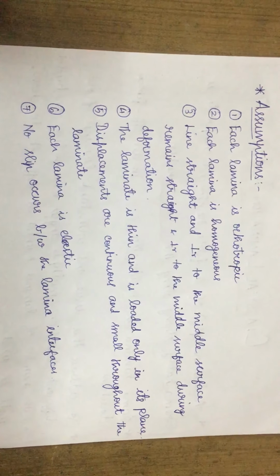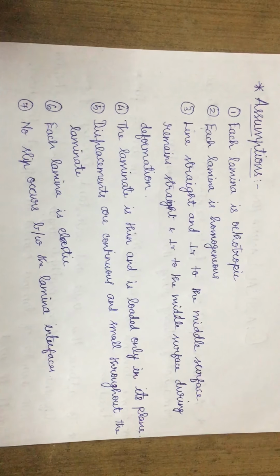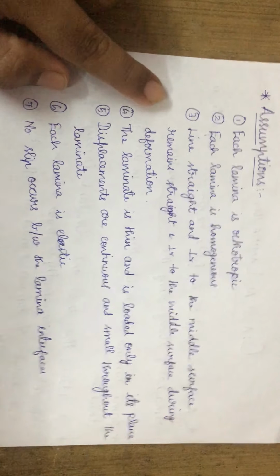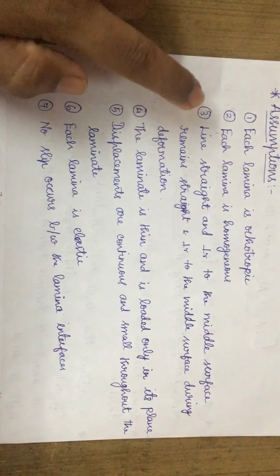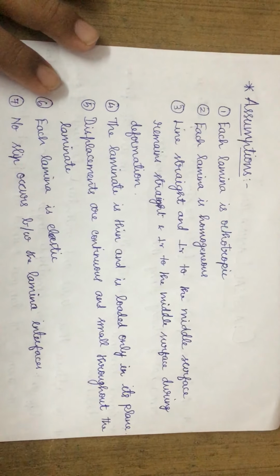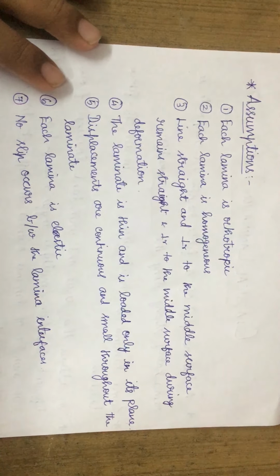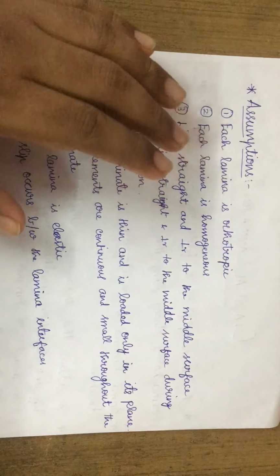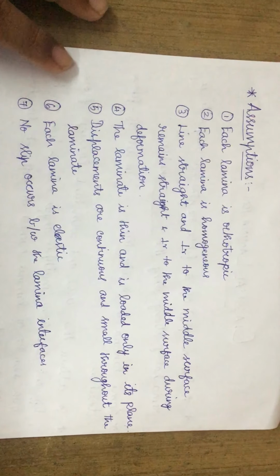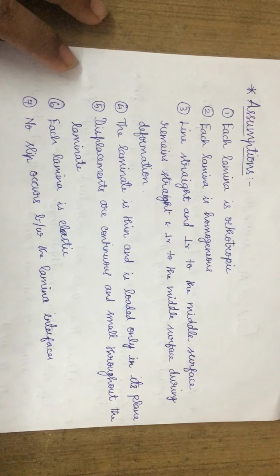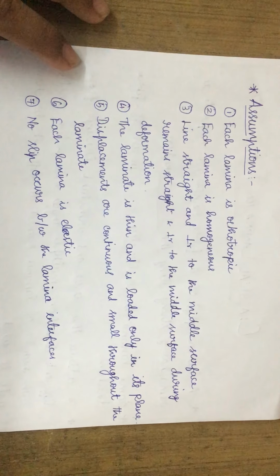The lamina is orthotropic, homogeneous, and elastic. And remember, a line straight and perpendicular to the middle surface remains straight and perpendicular to the middle surface during deformation. For laminates, this assumption is valid only for thin laminates. Displacements are continuous and small.